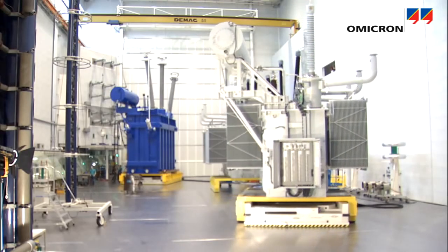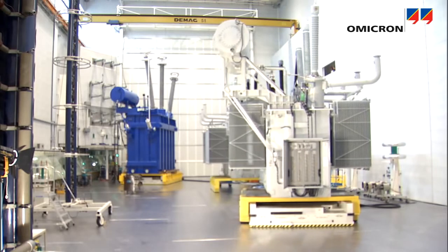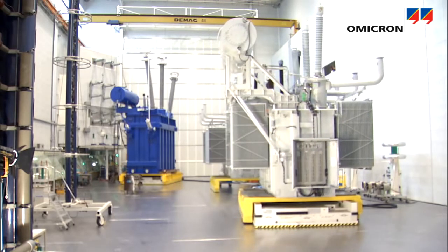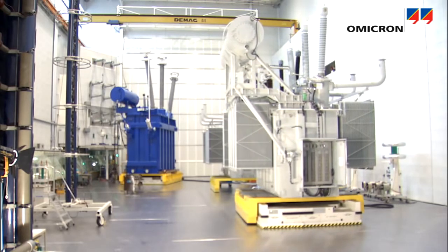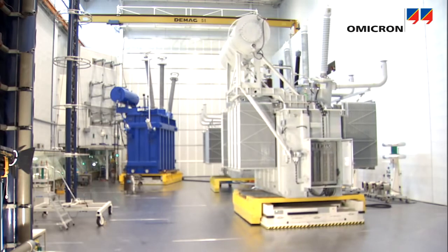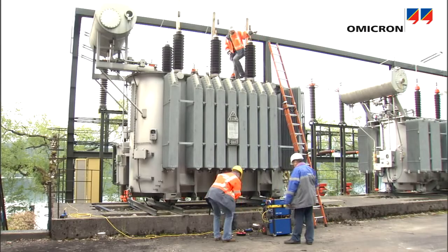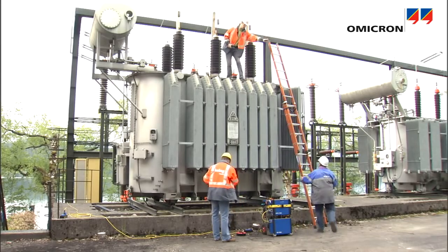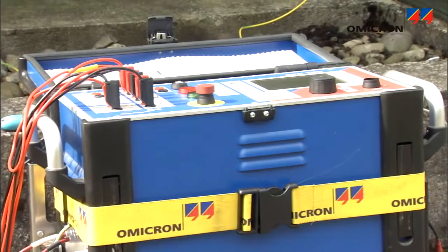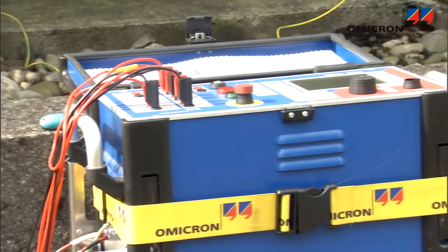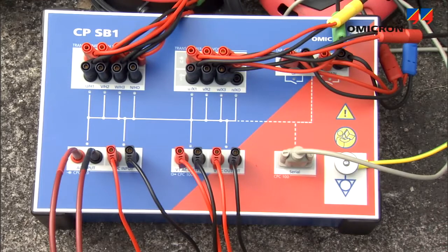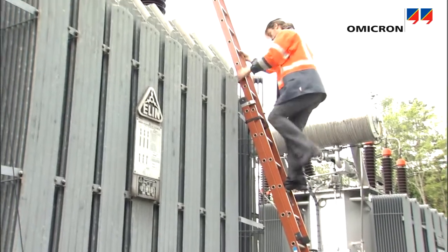When manufacturers perform ratio and winding resistance tests at the end of the production process or during factory acceptance testing, time is costly, and performing such tests efficiently is crucial. When performing diagnostic tests on-site, there's usually a limited window of time. The CPC100 and the CP-SB1 switchbox make ratio and winding resistance measurements efficient by avoiding climbing up and down the